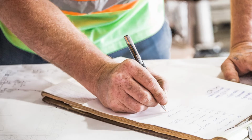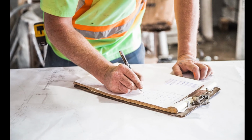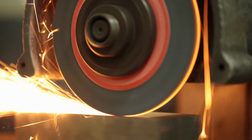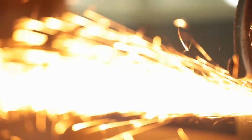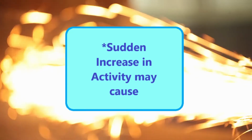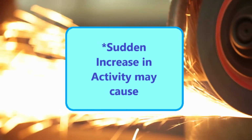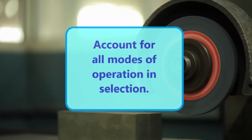Troubleshooting. With dynamic brake basics covered, let's look at 3 troubleshooting scenarios. Scenario A. My brake resistor gets too hot. Glowing visibly red, setting off smoke alarms, your resistor wattage is likely too low. An increase in the duty cycle can cause this, as well as poor resistor selection. Be sure to account for upticks in production when selecting your brake resistor.